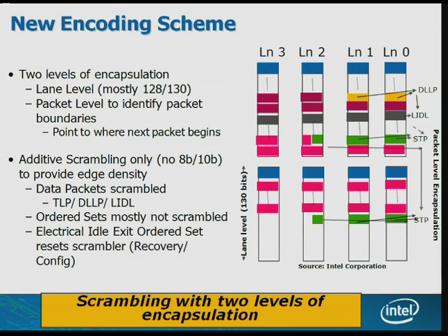In order to preserve DC balancing and actually provide the embedded clock information, the technique that is used is additive scrambling. The information, minus the synchronization characters, when it comes on the lane is scrambled on the transmit side and descrambled on the receive side. Transmit and receive mutually understand the algorithm for scrambling and descrambling, and that's done during the initialization, and could also be reinitialized during runtime.